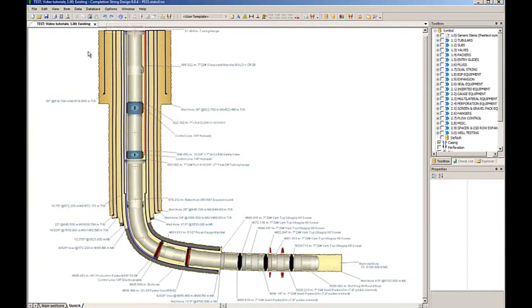Control points can be added or removed. To add a control point, click the right mouse button where you want to insert it and choose Add Control Point. To remove a control point, just right-click it and choose Delete. Note that the red crosses are only there to define the curve and will not be printed. You can always go back to the default setup by right-clicking and choosing Reset All Control Points.